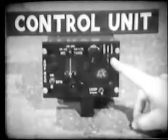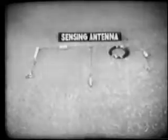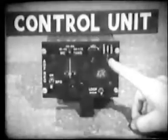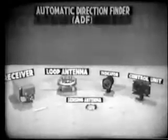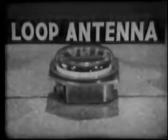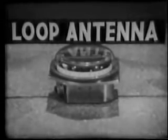In the antenna position, the receiver is connected only to the non-directional wire antenna and serves as a simple radio receiver. This position is normally used for tuning and identifying the station. In the loop position, the receiver is connected only to the directional loop antenna and serves as a manually operated direction finder. The position of this antenna with respect to the station will vary the strength of the signal received.